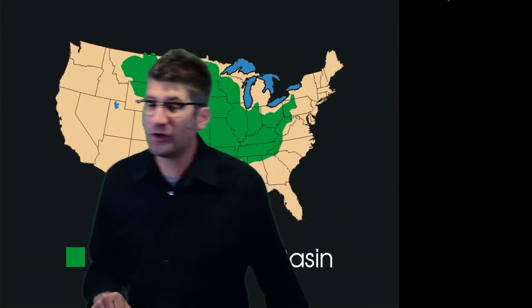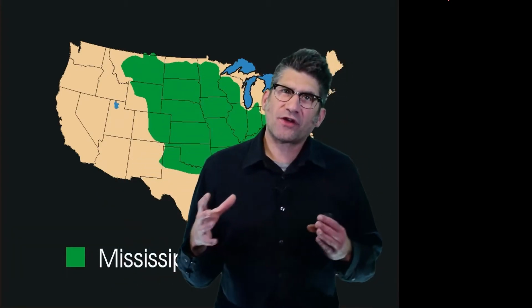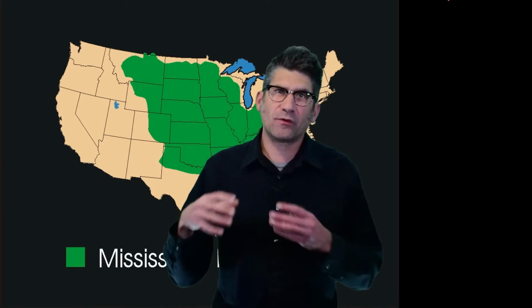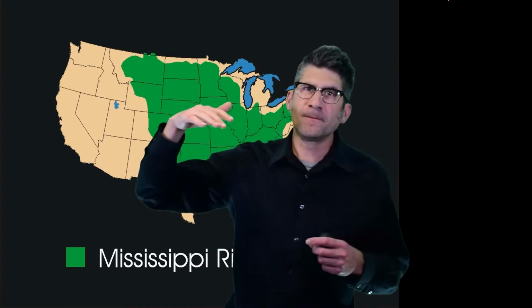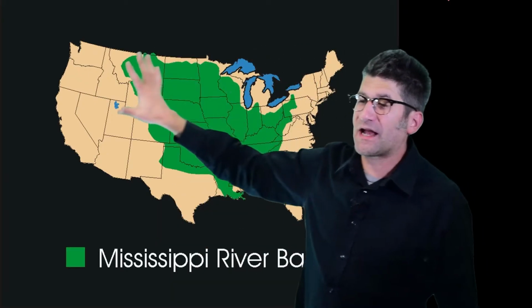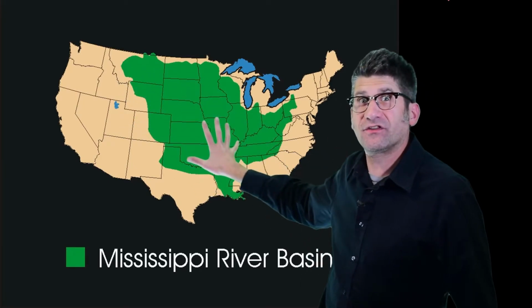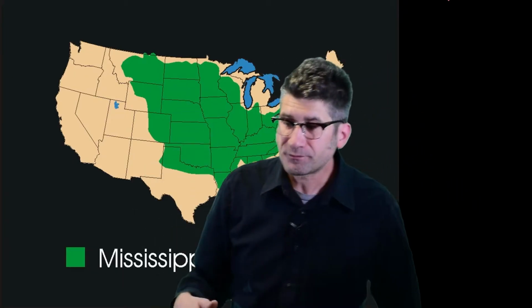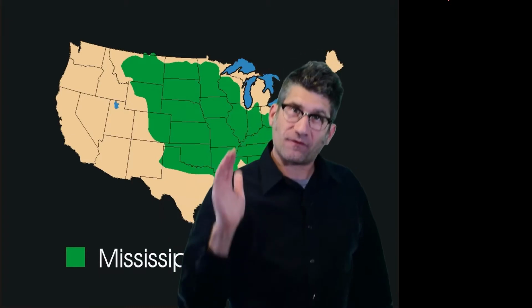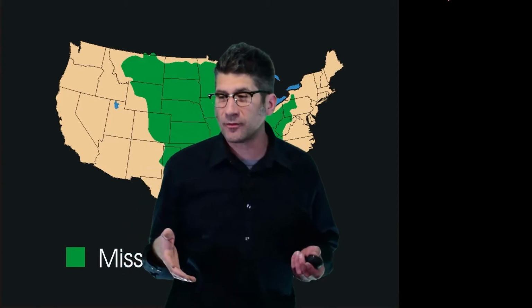Now, we talked about flood hydrographs earlier in the semester, and we talked about flashy floods associated with a peak discharge in a storm, where we might have a flash flood that occurs over a matter of minutes or hours. That's not what we're talking about here. We're talking about big massive floods. We're going to have a lot of water draining slowly through the Mississippi River drainage system. So these are floods that can take several weeks in terms of their flood crest before the flood crests go back down. And so generally these big floods are associated with abnormally wet conditions.